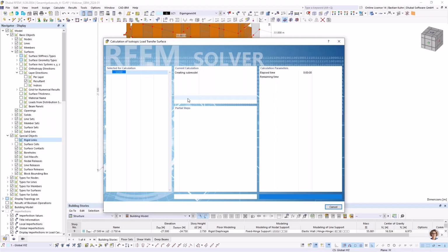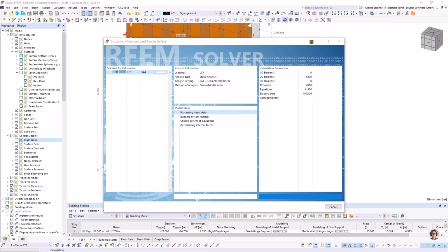Before we go to the wind load a little bit, I will also take a short look if there are remaining questions, but I'm pretty sure Richard will answer them all. Just opening them. Hold on. Okay, so far nothing remained open, and you see now it has divided the force here and is calculating the first load case. And when this is done, when the force is divided and transferred to every story, it will do 3 calculations. That's quite an important step inside. Yeah, generating the mesh afterwards.